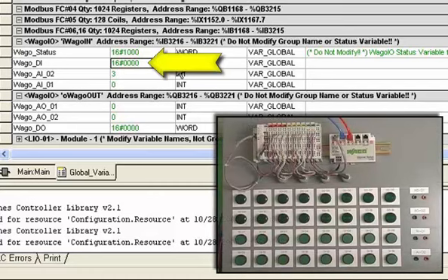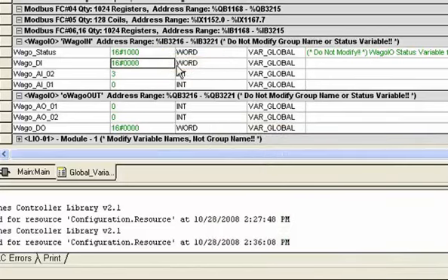So I turn on input 1, and that's bit 0, so I see a 1 in the monitor. Then I turn on input 2, that's bit 1, converted to hex, that's a 2. And I turn on input 3, that's bit 2, which in hex is 4. And finally input 4 is bit 3, so you see the value 8.